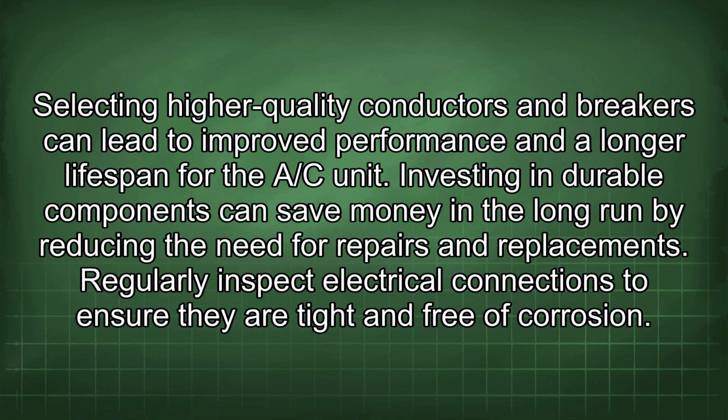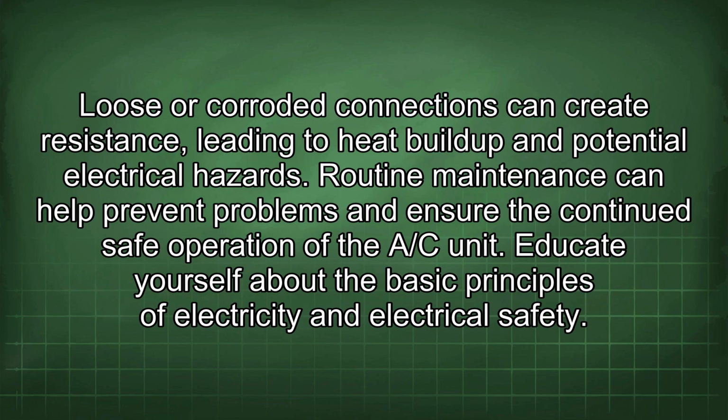Regularly inspect electrical connections to ensure they are tight and free of corrosion. Loose or corroded connections can create resistance, leading to heat buildup and potential electrical hazards. Routine maintenance can help prevent problems and ensure the continued safe operation of the A/C unit.